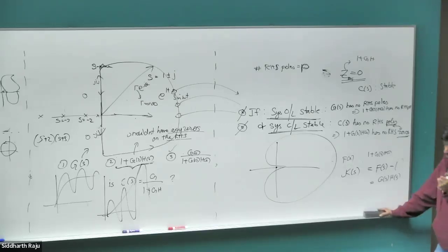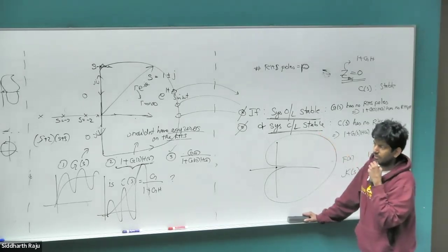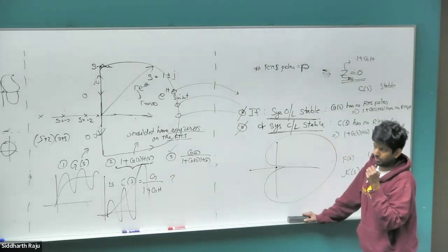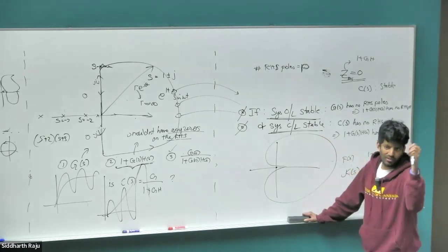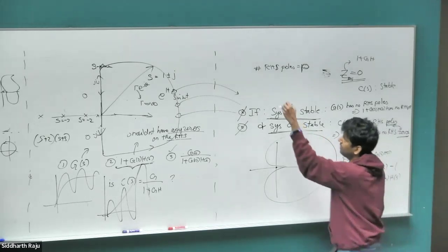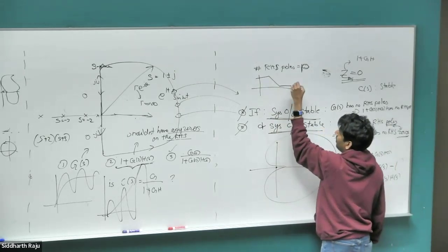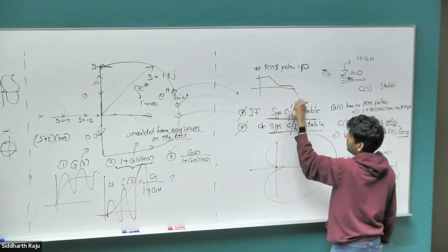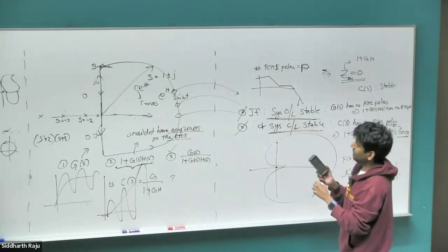Because typically when you have a complex system, you won't have those nice equations. In a typical industrial system, you will take a frequency analyzer, put in different frequency sine wave signals and look at how the response looks. Depending on the slope of the response, you would get different kinds of responses. We'll get to Bode plot in a minute, but you might have plots that look like this. Just by looking at this response, I can tell you exactly where the poles and the zeros are.